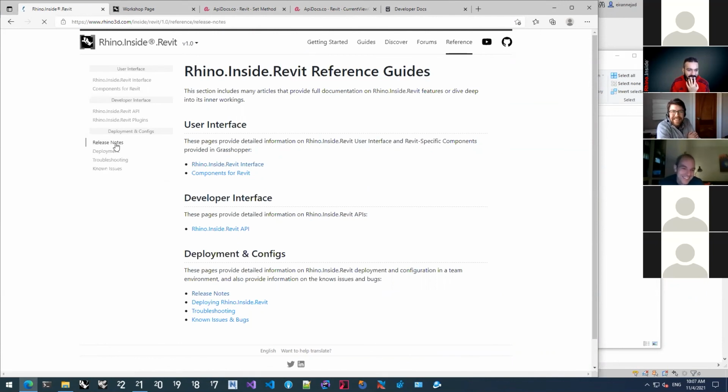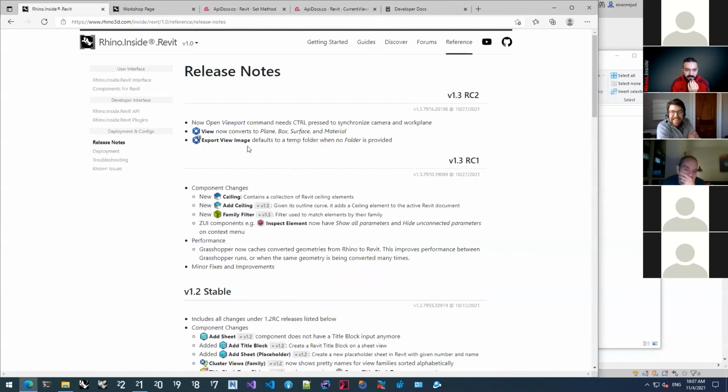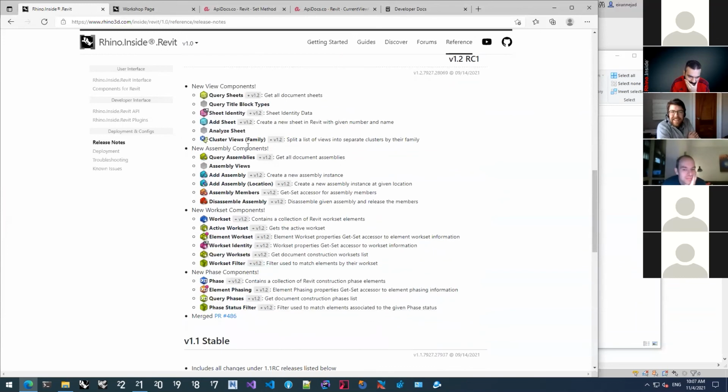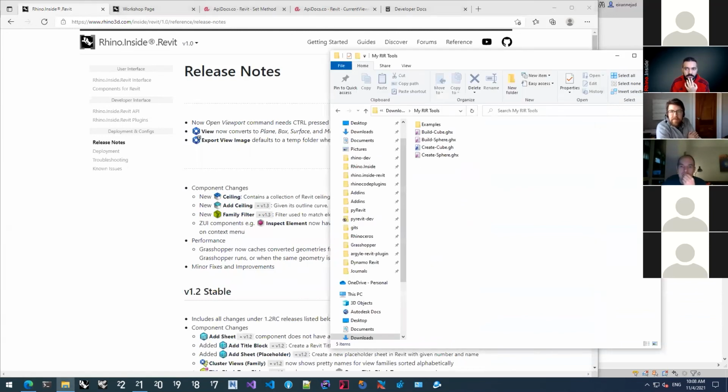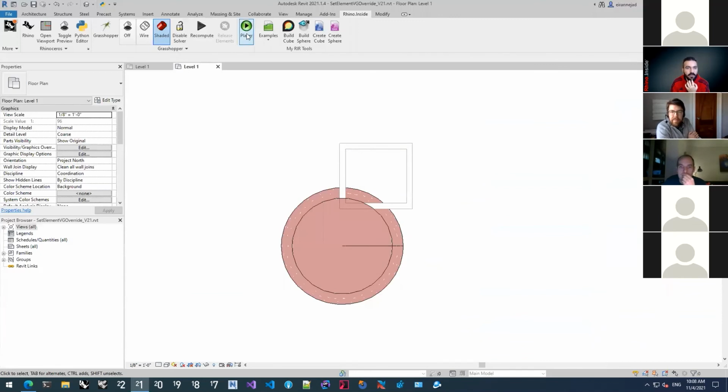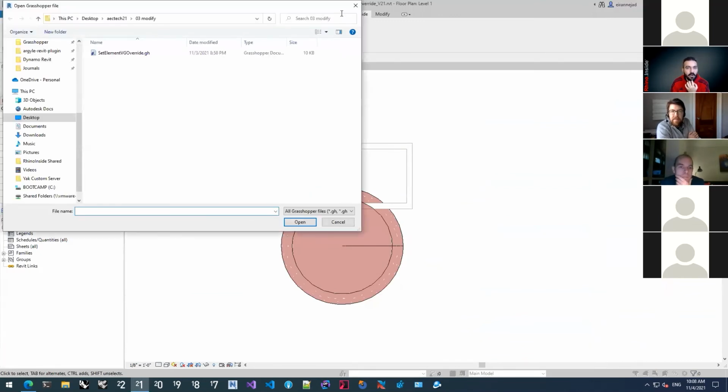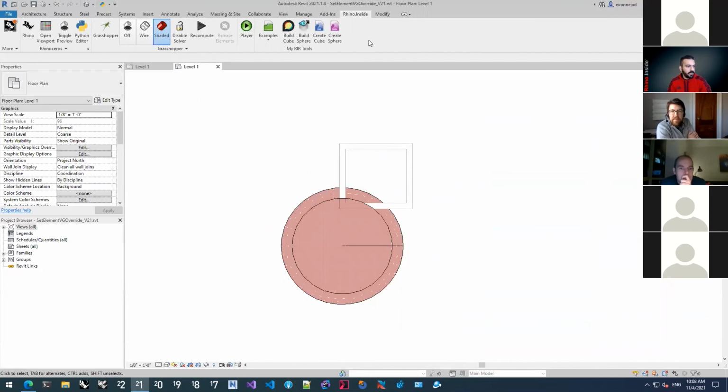And on the flip side, if you use PyRevit already in Revit, PyRevit can call into Grasshopper Player scripts too. So you can have buttons alongside your Revit scripts using PyRevit and Grasshopper scripts called. So I can either run it from here through the Player, or if you have PyRevit installed and that's what you're using, you can just throw the Grasshopper definition inside a PyRevit bundle, and PyRevit will ask Rhino.Inside.Revit to run it for you.